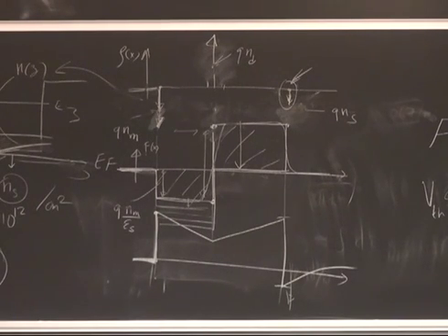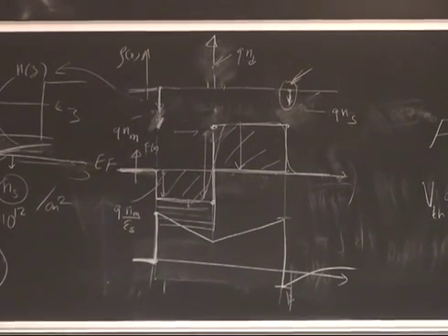Yes, that's right. So basically what we are doing is we are connected with a gate voltage, with a battery, to the Fermi level of the metal, okay, and we are applying a voltage here, and the one I was discussing now is a negative voltage. So what's going on when I apply negative voltage is this is getting pushed up. We're going to sketch the band diagram now. Okay, let's look at this.